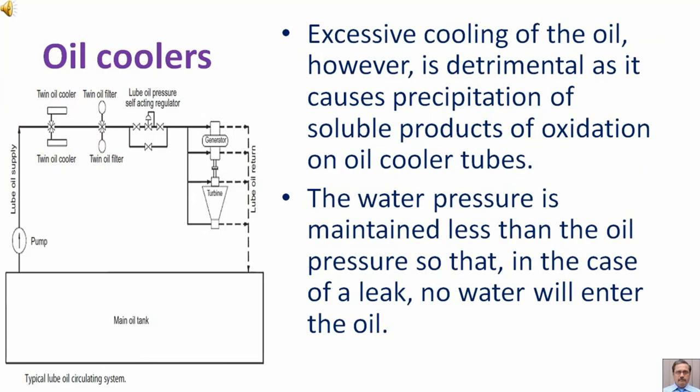Excessive cooling of the oil, however, is detrimental as it causes precipitation of soluble products of oxidation in oil cooler tubes. The water pressure is maintained less than the oil pressure so that in the case of a leak, no water will enter the oil.